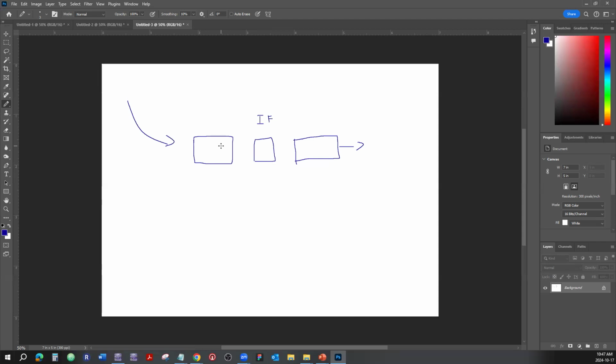Now, if you take that high frequency carrier and translate it into another carrier that is lower, you only need to have one good processing and amplification system that is tuned to the intermediate frequency in order to process the signal properly further down.